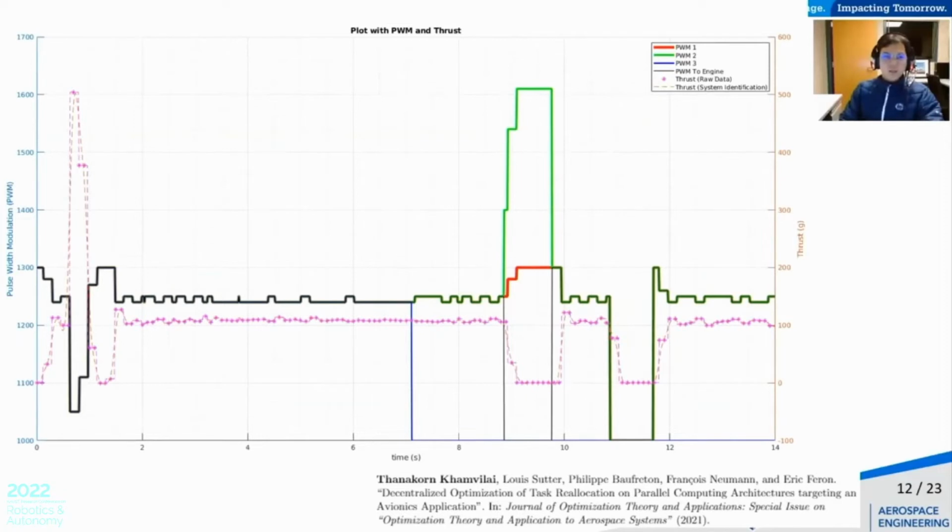When failures were injected and the controller applications were dropped, the PWM signal sent to the motor becomes 0. If at least two signals match, the motor remained in operation. If none of them match, the motor will be stopped. So, as in the case where the controller applications were dropped.